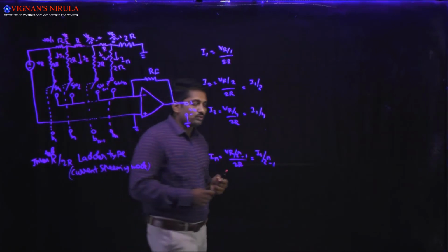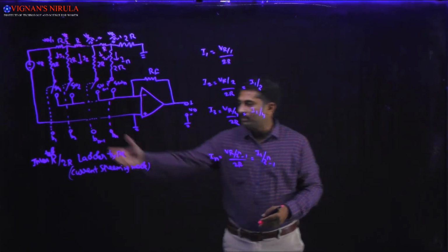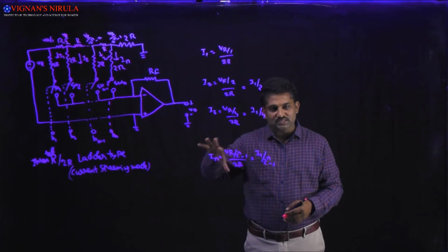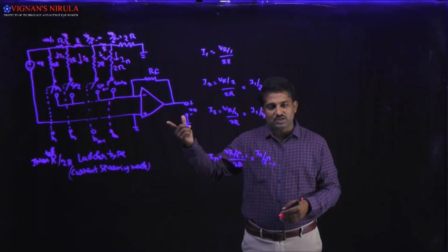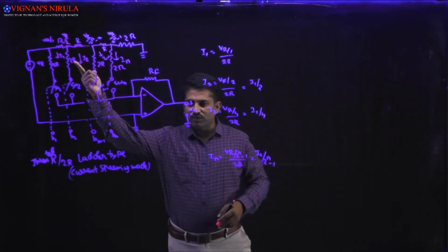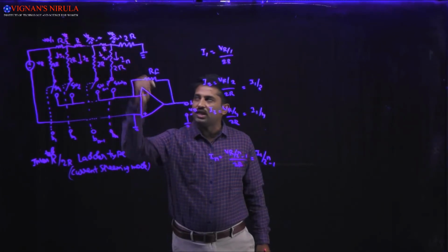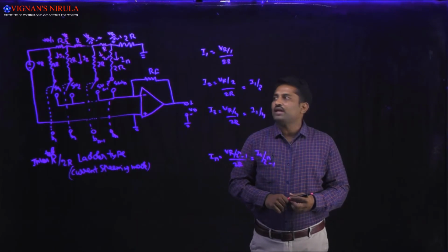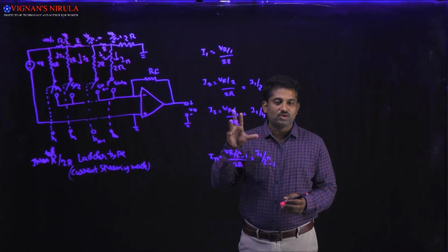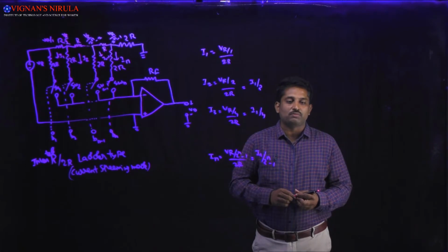And one more thing you have to remember in this inverted R by 2R ladder type technique, whatever binary input you have chosen for the input values, that means whether it may be 1 or 0, the node voltages are always constant. That means at the first node we are having VR by 1, and at the second node we are having VR by 2, and so on. At the last node we are having VR by 2 to the power of n minus 1 into R. Node voltages are the same irrespective of the input voltages applied at the input terminal. Because of this,